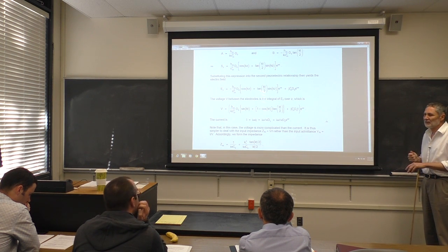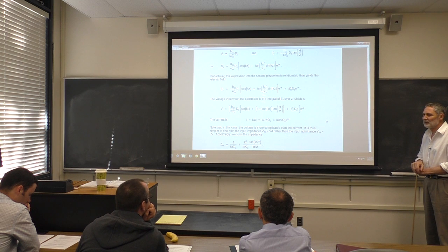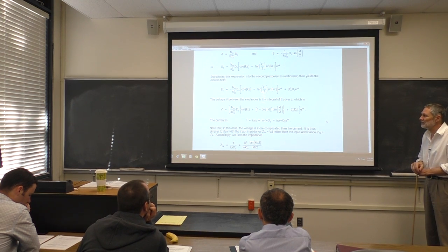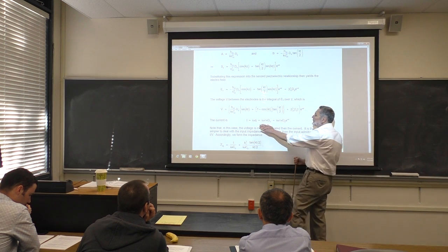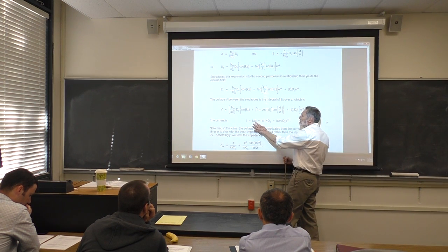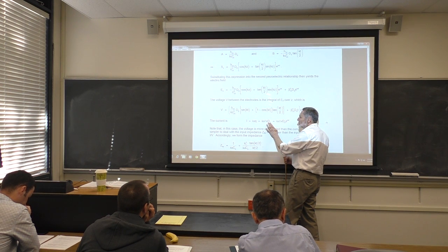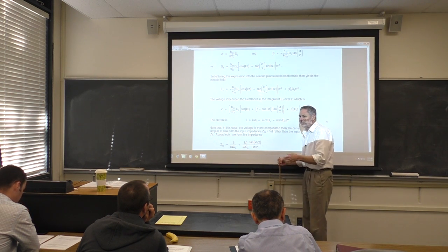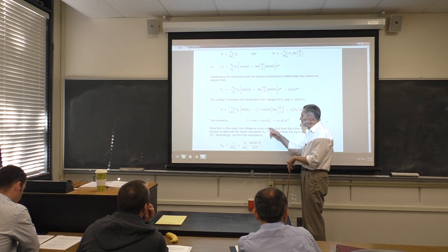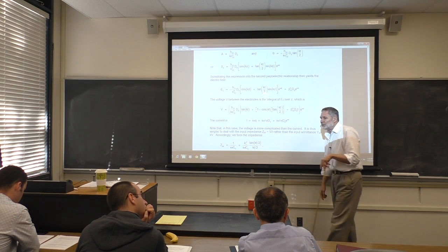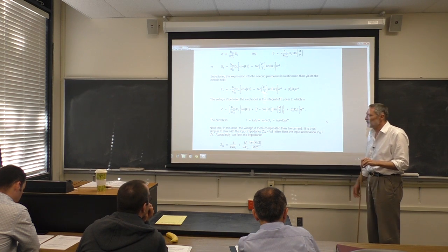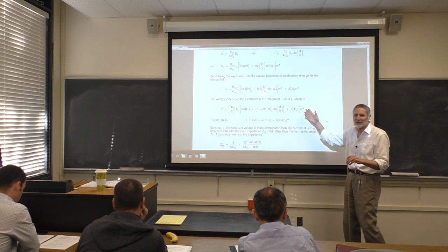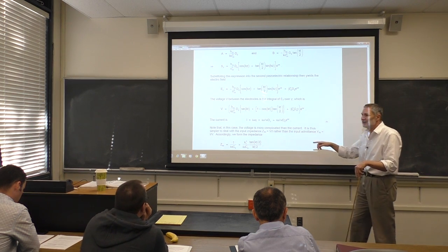Now, this is a little bit different than before. Before we dealt with the current, and it was complicated, and the voltage was simple. But now the voltage is complicated, and the current is simple. The current, as we've seen several times before, is i omega times the free charge. The free charge dictates the displacement field, so you use Gauss's law for dielectrics or macroscopic media to get this. So now, are we going to deal with the admittance? No. We're going to deal with the impedance, right? We don't want to deal with 1 over a complicated quantity like that.